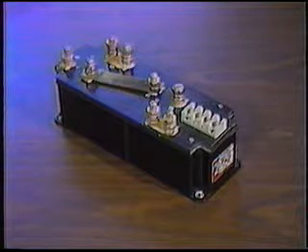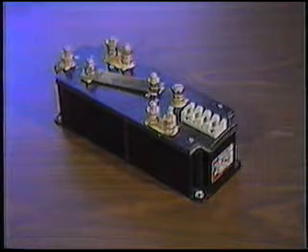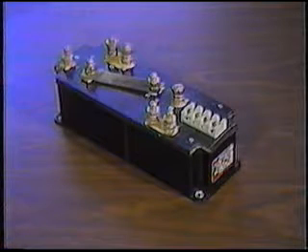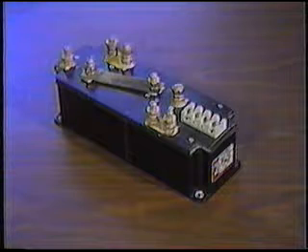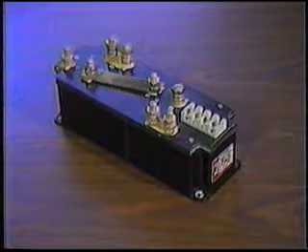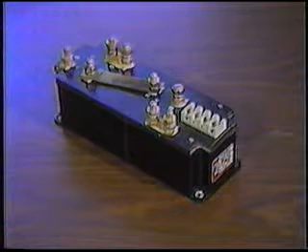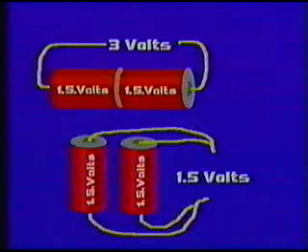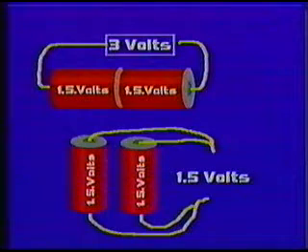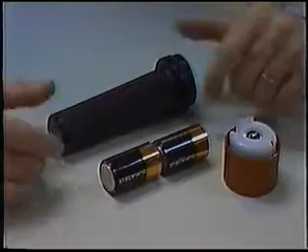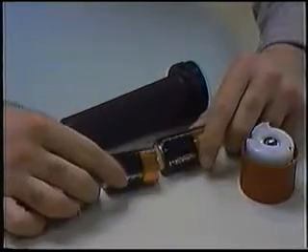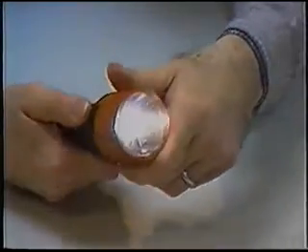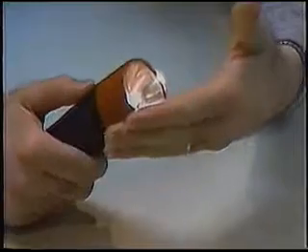In our previous program, we mentioned a device called a series parallel relay. Let's now discuss the function of this component and the effect it has on the electrical system. Remember that electrical loads can be connected in either series or parallel. Electrical sources can also be connected in series or parallel. When sources are connected in series, their total output voltage is the sum of both sources. A classic example is an ordinary flashlight. Each of these batteries has a voltage of 1.5 volts. But when we install them in the flashlight, they're in series and have a combined voltage of 3 volts.